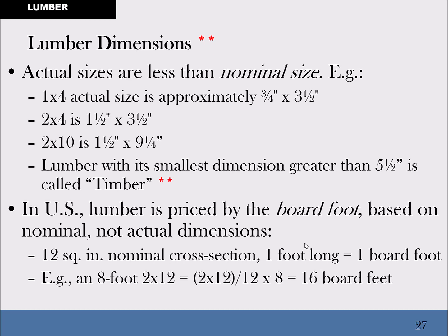But in reality, they don't worry about making those boards exactly that number when they're planing them out. And so you can't completely go by that. It's true in theory, but in reality, if you take a long enough 2x12, you measure at one end, you might measure 11 inches instead of 11.25.